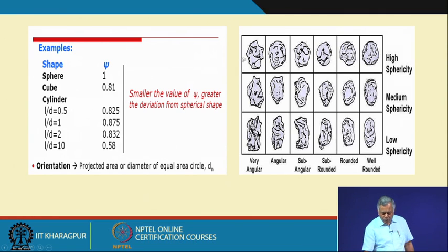If you look at these particles, and if you calculate, and even look under a microscope, they are very close to a spherical shape. For a perfect sphere, this value of psi, that is the sphericity, should be 1. The more departure from 1 towards 0, the farther it is from a spherical shape, going towards the flaky nature.